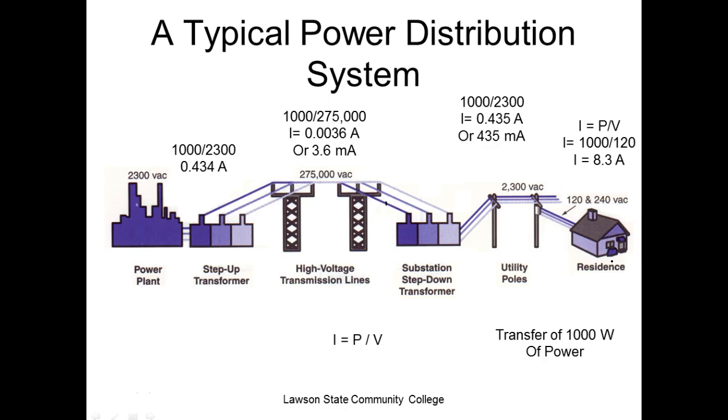No, because you're not paying for 240, you're paying for power. What it does is allow them to run smaller conductors. So now I can run those conductors through the wall instead of running them under the house. It's going to be cheaper to install, but it's not more efficient to run. And a lot of people think that.